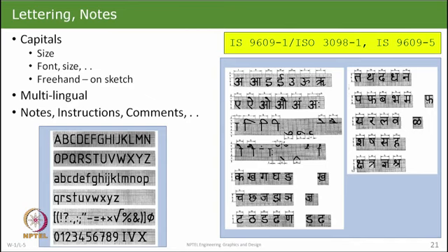So, largely you will see that being followed, although if you are doing some word processing, you will find you have hundreds of fonts. Well, on engineering drawings we do not use that many fonts, there is a certain set of preferred fonts. So, size, sketch, that is decided and you can pick up from there. By and large, when you are writing titles and everything, one generally uses only capitals. One generally does not use lowercase letters. Dimensions, decimals, they are all numerals like that.